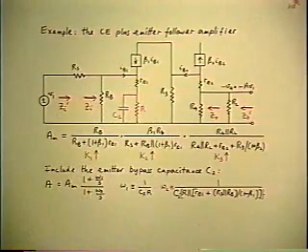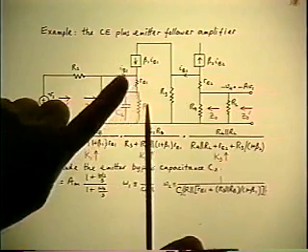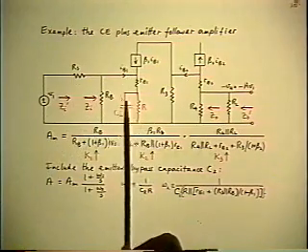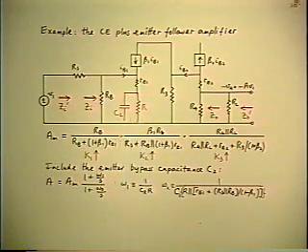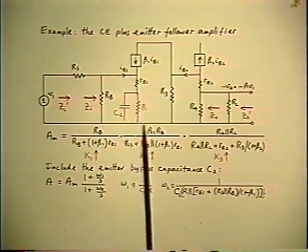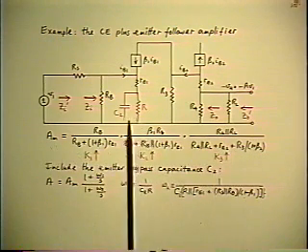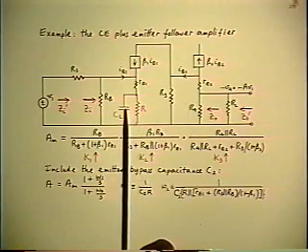Now we'll do the same thing, starting again from a slightly different position, and that is we've got the mid-band gain in which both of them are absent, but we can count only the C2 as the extra element, simply by considering the reference condition to be when the extra element is a zero impedance. Because when it's a zero impedance, it bypasses out the resistance anyway. So we can still use the mid-band value of the gain as the reference condition, and yet use the capacitor by itself as an extra element.